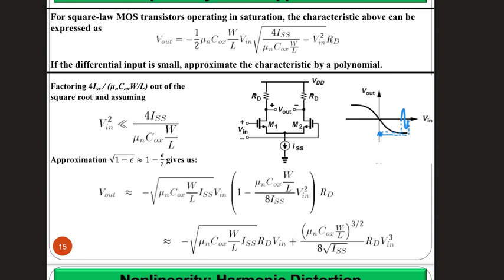This is different from the MOSFET saturation. It's going into amplification saturation, but to differentiate that, we call it the compression region. So your amplifier has gone into the compression region. Why? Because this term started to dominate at that point, and because it's a negative term, it's going to take out a good amount of the positive term, and then eventually you end up with very small output coming out of this circuit. We call that the compression. Tamam? We will look at it in a couple of slides.